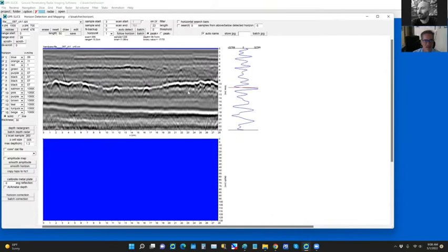The next step is, let's say we want to detect this horizon here. We go to horizon number 2, and then we set a sample start and a sample end. Right now it's set to 170 and 300. But we hit this button here called horizontal search bars. It can say that we're searching just in that location of the radar ground. We can set it to work on the peak plus response of the pulse or the peak minus. Right now it's set to the peak plus, and we'll just run an auto detect on it right here.